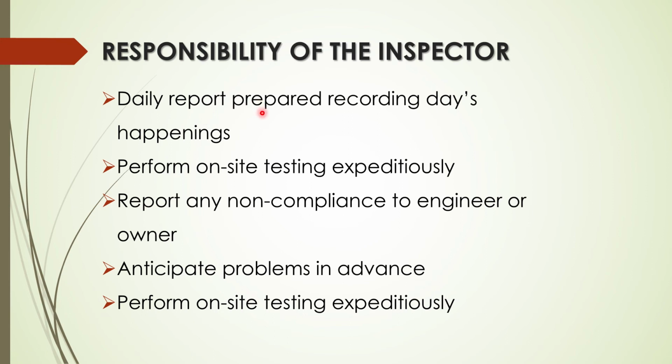Daily report: prepare recordings of the day's happenings. Perform on-site tests expeditiously. Don't hold them up. Be ready. Report any non-compliance to the engineer or owner. Anticipate problems in advance. Try to say, oh, that's not going to pass, so maybe you can help them, but just be careful of that. Typically, they'll call you at the last minute and everybody is breathing down your neck, but you need to do your job in a quality way.